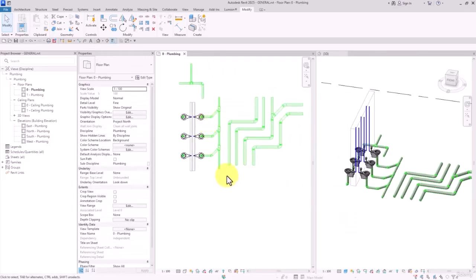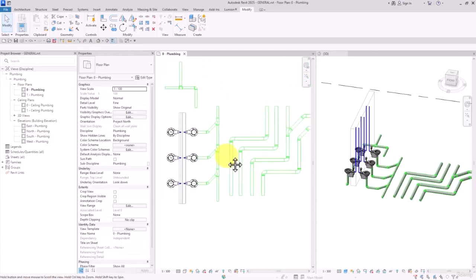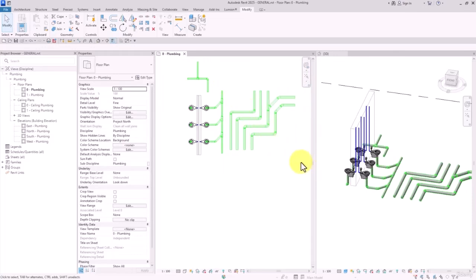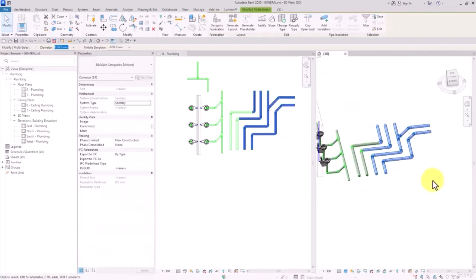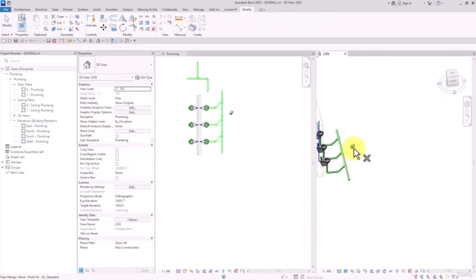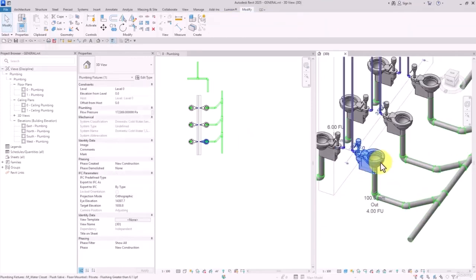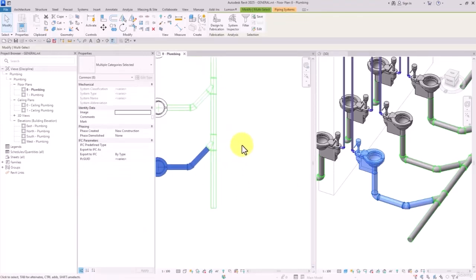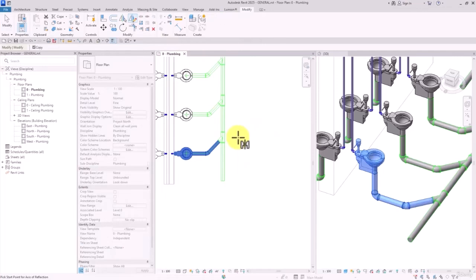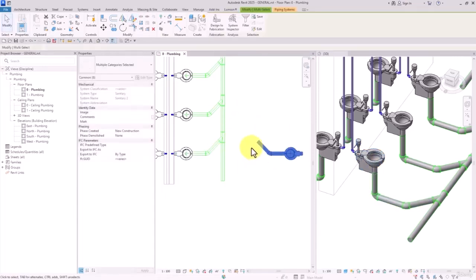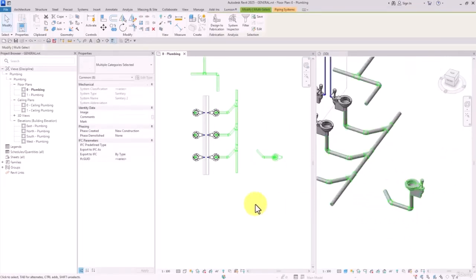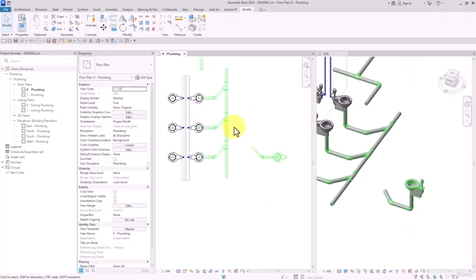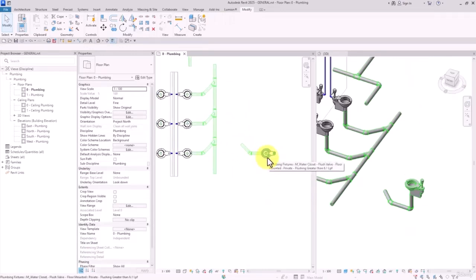However, if you didn't have such objects such as this wall here, you need to use mirror draw axis. Right, as an example, let me go ahead and remove these elements. Okay, here we go. And then I'm going to select this object here, and I want to mirror it to this side. So I'm going to select mirror draw axis, draw a line here, and here we go. See? The object easily got mirrored to the other side of this line that we've just drawn. This is very useful.